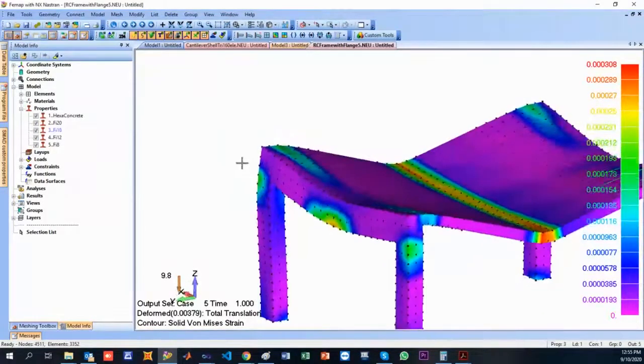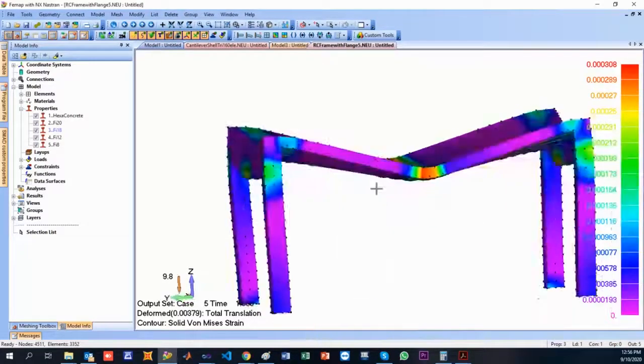Okay, so what do you notice? A slab failed in Durban, and 1 person was killed, 3 were injured. Reminds you of something? Anybody? Does that make sense? The results? Now that we removed the longitudinal reinforcement from that area, you see we have plastic hinge development at the slab level, right? The entire slab, in this case, developed a region which is damaged, which resembles a plastic hinge.